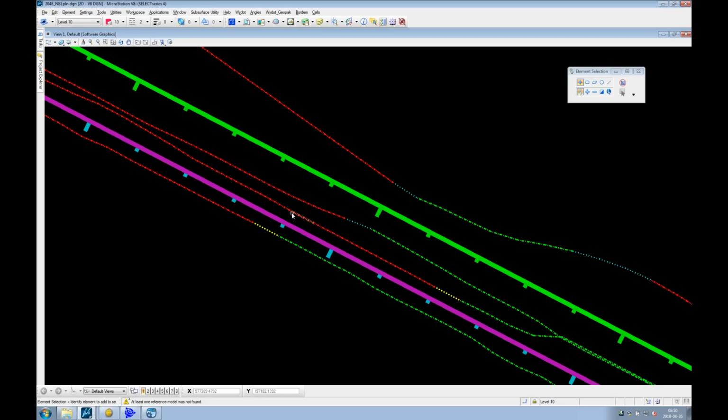And basically we'll just export this line work or these vertices from this line work. That's where all of those design slope stake points come from. So all these vertices on these tie down lines, we'll elevate that against the original terrain model and then export that out as a CSV file. So point number, northing, easting, elevation, feature code. Okay.